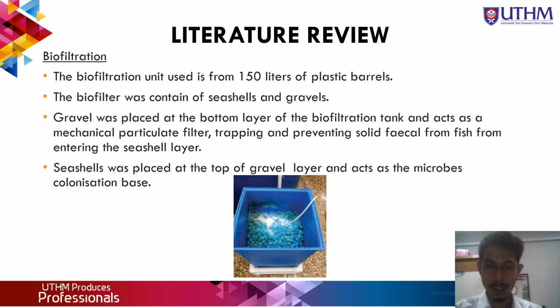The seashell and the gravel are placed into a 150-liter plastic barrel, where we fill the bottom layer with gravel and the top layer with seashell, because the gravel can act as a mechanical particulate filter, trapping solid fecal waste from the fish and preventing it from entering the seashell layer.